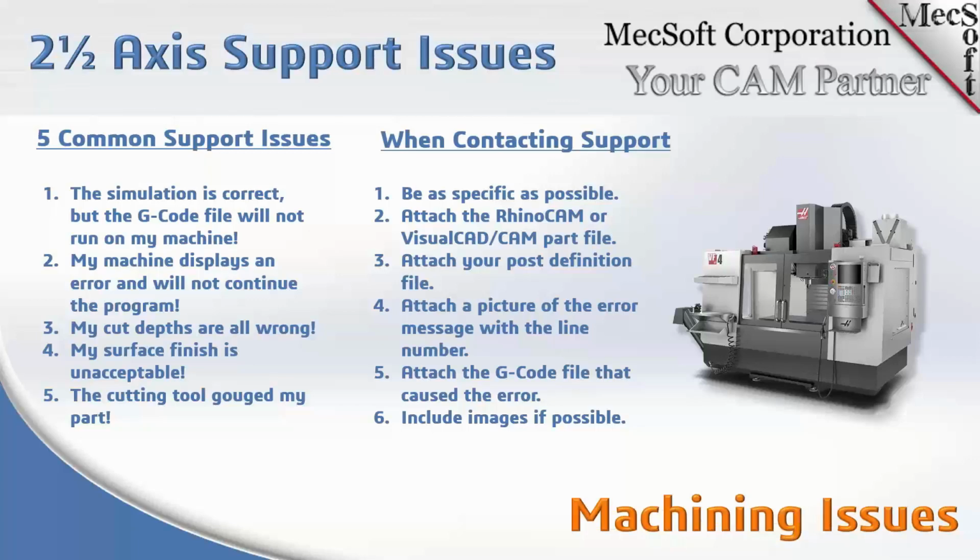In the default parameters, at factory set parameters, when you load the program, it's not tuned in for the most accuracy because there's some overhead involved. Anytime you increase accuracy, you're going to have more computation time. So the factory defaults are set for the most common uses. You can adjust those if you need more accuracy. Typically, you won't loosen your accuracy unless you've got a really large part and you're not worried about accuracy. You can loosen it to make the processing go faster.